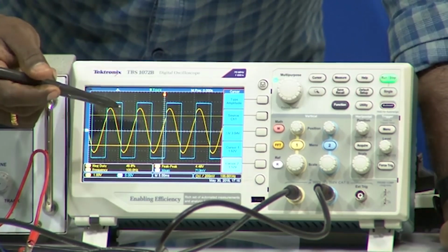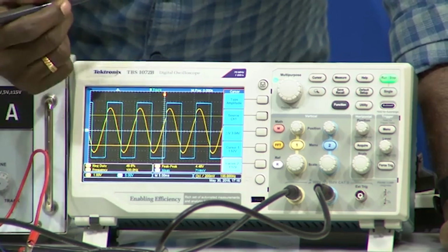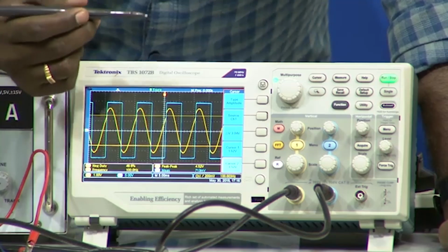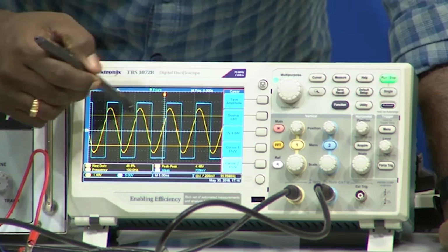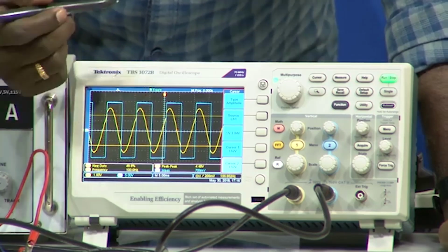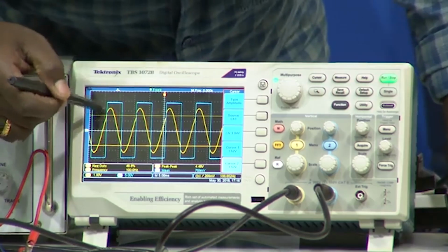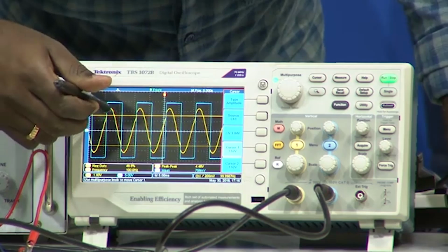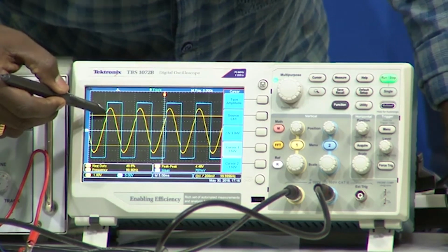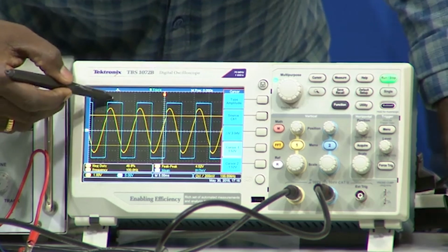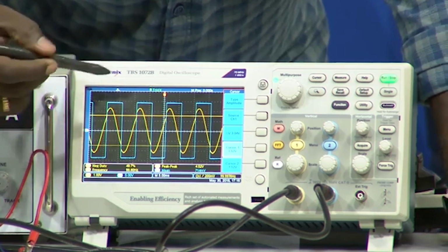Now, is it correct or not? How do you understand whether it is working as we expected? Our expectation, as per our theoretical or simulation results, was that when the input voltage, in this case the yellow sinusoidal input, is greater than the higher threshold, in this case plus 1.5, I should get plus VCC, which is 15. So, now if I see, this is my input, this is the higher threshold value. When the input is greater than this higher threshold, the output has gone to plus VCC, isn't it? Meaning the circuit is working as expected in the higher threshold.